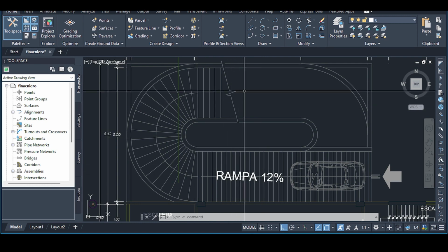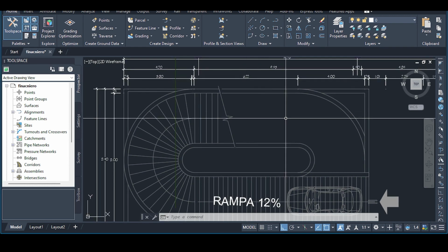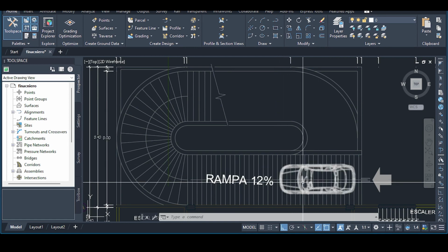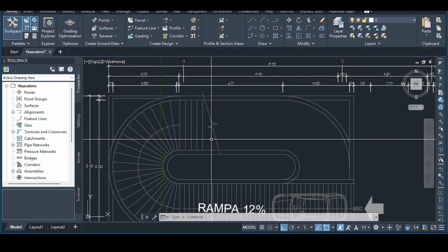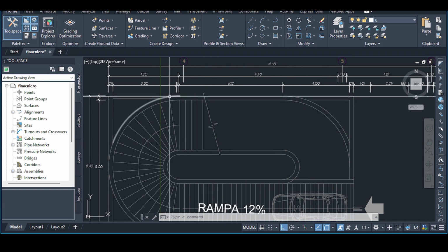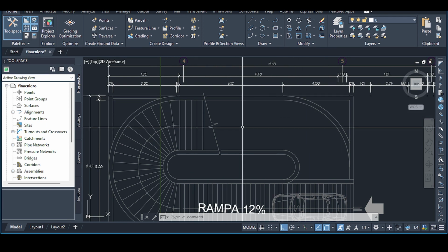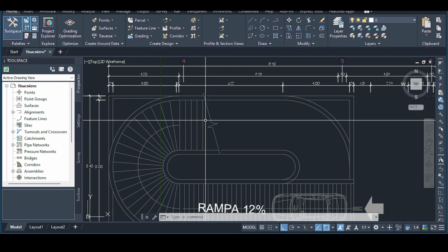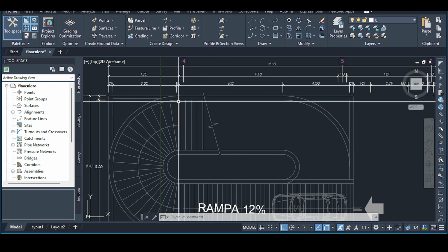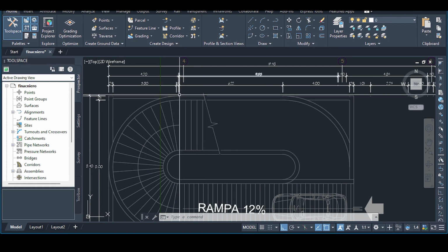One thing I forgot to mention is that it's very hard for us also to have a ramp because there is a retaining wall, right? The ramp needs to be carried somehow. Now, having the retaining wall carry the ramp is really odd because you would have to provide some links in the wall, and it's really a mess. You don't want to do that. Also, car ramps need to be sturdy enough. So connecting it with a 250 millimeter wall that is already under pressure from soil, I don't think it's a nice idea. I think this is not good.